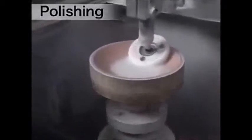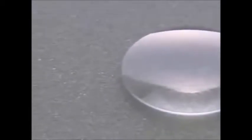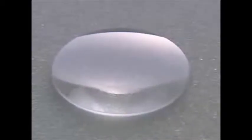Using an abrasive sheet-lined platter, lenses are polished until the surface roughness reaches the specified level to the order of a submicron. At the same time, the surface curvature is also precisely adjusted. During this step, the surface of the lens becomes more and more transparent. Both front and back surfaces of pressed glass, initially opaque, are polished to achieve a transparent lens.